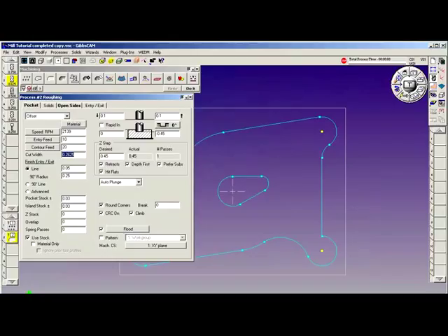That is the length or the width of the flat at the bottom of the cutter that is available after the radius. So we have a 5/8 end mill with a 50 thousandths radius. So if you divide 5/8 by 2, subtract 50 thousandths, you end up with 0.2625. This ensures that we get a proper cleanup as we step over in the pockets.